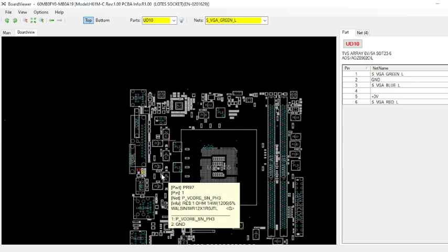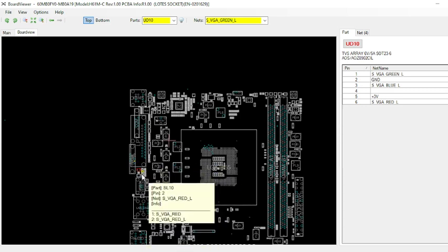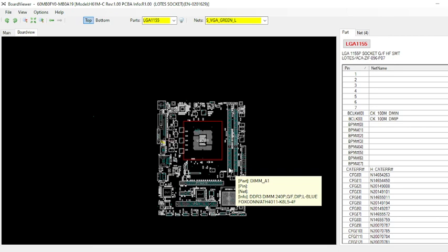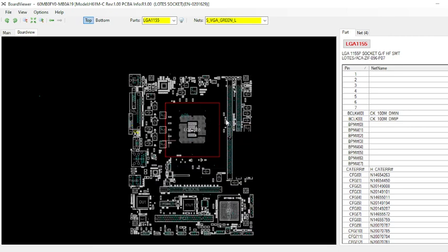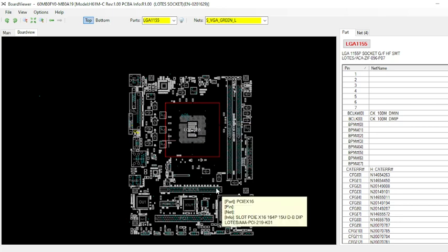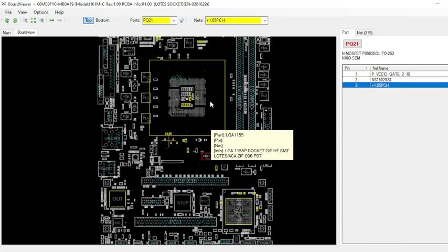You will get display on VGA after you just replace these components, solving your display problem. Okay, this was all about the ASUS H61 motherboard, in which we don't have CPU VTT because our PCH supply is given as an enable to the Vcore IC.